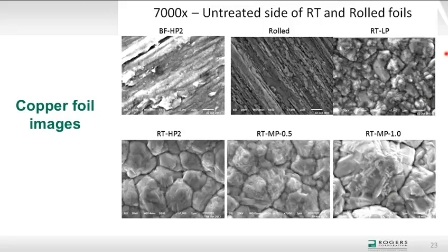And if we look again at the same magnification, and these are the same foils in the same locations, you'll see that the structure looks quite different. They are now nodule-free. Again, if you're looking carefully at the roll, you can see the effect of the rolling process in aligning the copper grains. This is looking at the bath side of the reverse-treated foil that exhibited a very high profile.